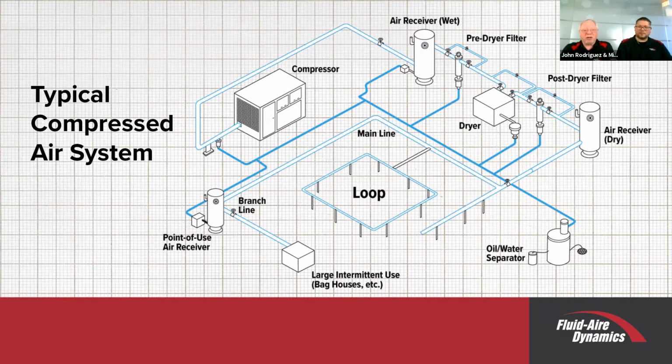So instead of, let's say, a 2-inch pipe, a loop will now act like a 3-inch header. It makes sense because if you have one unit, a CAC on one end and a lathe on the other, and they both need air, again, these are just examples. If they're both running at the same time, they'd be able to, and anybody else that needs to use the air is able to do so.